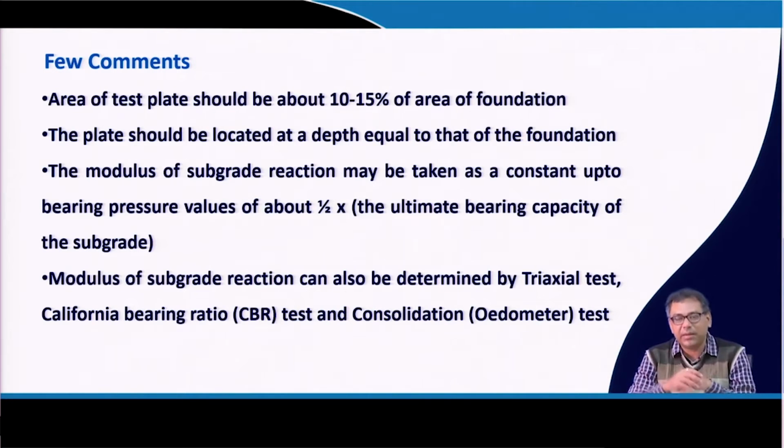So, in that case also you have to apply the depth correction, but in that case the depth of foundation should be the difference between the depth of foundation and the depth of plate. Remember that. If it is a surface test, then the depth of foundation is equal to the depth of footing where you placed your foundation. But if the plate load test is done at a certain depth less than the depth of foundation, then the depth of foundation in the equation given in the depth correction factor will be the difference between the depth of foundation and the depth of plate. Clear? Okay, so that means the modulus of subgrade reaction may be taken as a constant up to a bearing value of about half the ultimate bearing capacity of the subgrade.